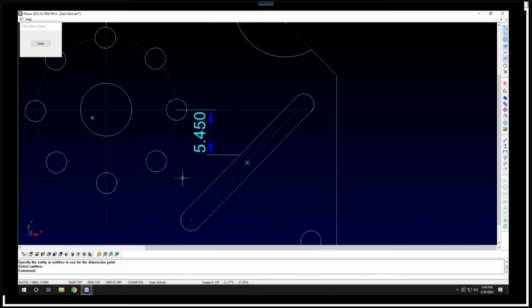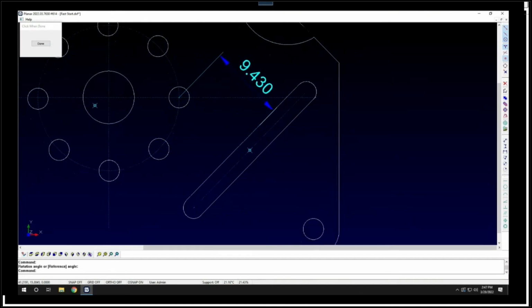Pick that center there. Next, I'm going to do a command in the bottom left-hand corner, and I'm going to type the word rotate. From there, I'm going to rotate what? This dimension from the center axis here. I'm going to rotate it all the way down here. Now, I just need to grab this line, drag it to the center of this part, and you can see now I am perfectly aligned to this feature right here. That is exactly the dimension I'm looking for.